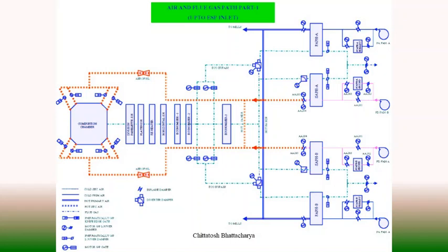Now after the combustion, whatever product is there, it is passing through various heat traps, like heat is absorbed in furnace water walls within the evaporator chamber, then primary and secondary superheaters, then reheaters, then economizers, then air preheaters, and after that it is passed through the ESP and mechanical dust collectors, and then it is evacuated by ID fan and disposed through chimney. So naturally we have PA fan, FD fan, igniter fan, ID fan.